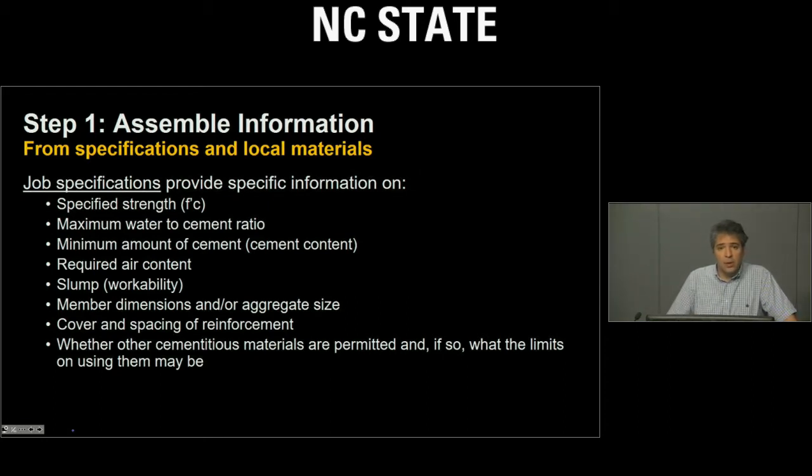For example, the owner of the facility or the owner of the structure that you are designing this mixture proportion for might specify a certain maximum water-cement ratio, or the maximum water-cement ratio might be specified because of the exposure condition. We will talk about those. Are there any minimum amounts of cement? What is the required air content?